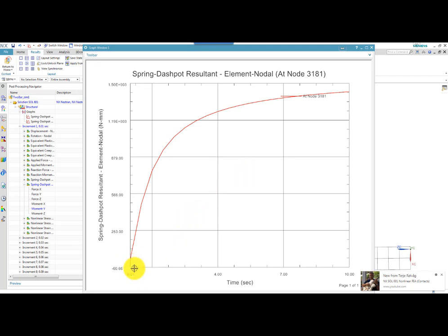The load is increased as a function of time, but you see there is no linear relationship between the torque and the applied force, because the cosine of the angle approaches 0. That means that if you continuously increase the load, the resulting moment will not increase that much, because the arm is going to almost 0. When you approach 90 degrees, it will be absolutely 0. And then you will add no more torque, and the system will stop. So this is the nonlinear effect.